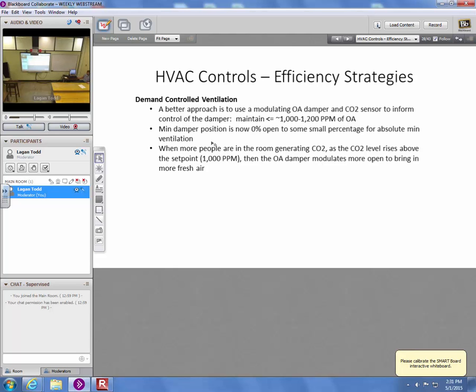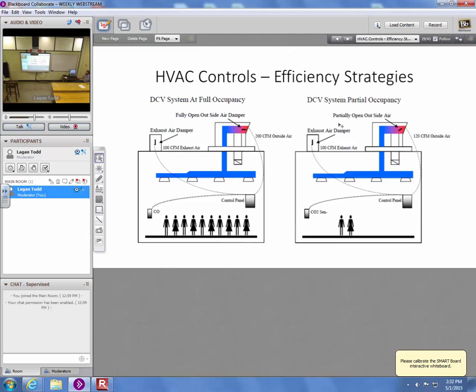Yeah, and the install. A typical cost for DCV points installed is anywhere from $300 to $1,000 a point. If you were to have a controls contractor come in to do demand control ventilation on one air handler, where they have to put in a CO2 sensor, maybe several, but then also do a couple hours of programming and a few hours of making sure it all works, you're $10,000 into it before you know it, and if you didn't make it work right to actually save energy, the payback time's quite extended if you don't actually implement the changes. Yeah, I suppose. Okay, makes sense.